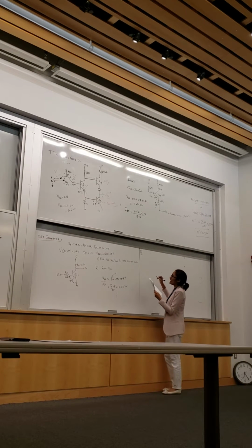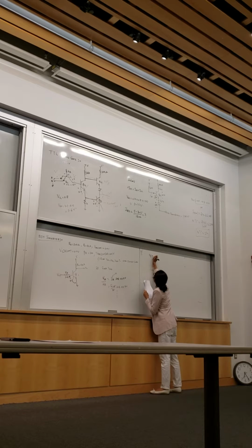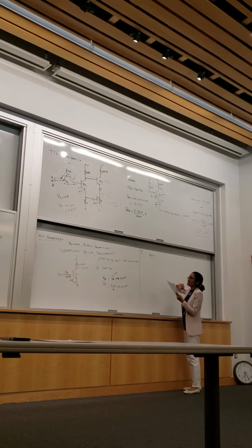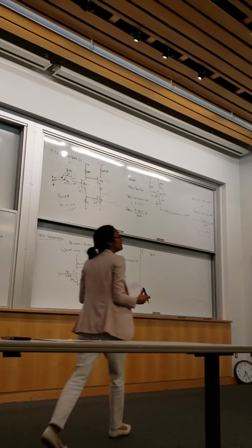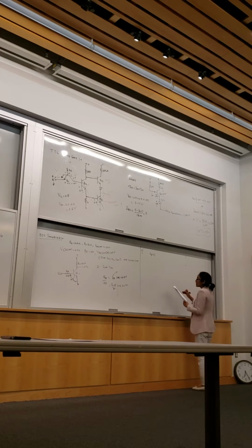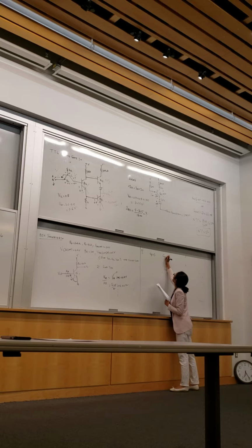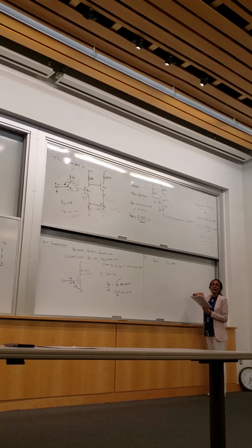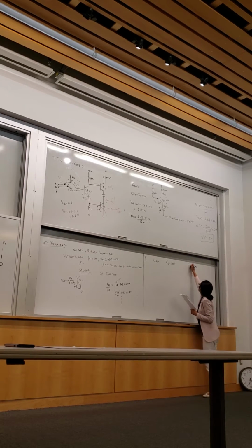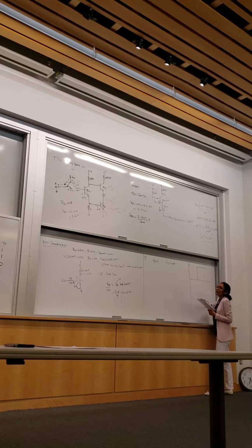So the third part of this problem is you have to find TF for this inverter. I have to look at the time. It's 25.6.4. So we have to find TF for the inverter when you have 100 picofarad load capacitance. You have to calculate the fall time. Do you remember the waveform? It comes when input goes high, right? Input goes from 0 to 5 volts. I should have provided that.